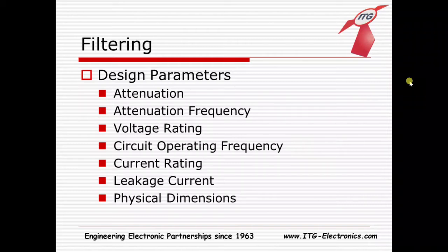You might get maybe 180,000 hertz, you'll have a big spike, and you're not exactly sure what that is. It's not coming from anything else. It's probably a harmonic of that 60 hertz operating frequency. So there's some various things you can do about that, but being aware of the operating frequency of all the different subsystems within your circuit is very important for tackling noise.